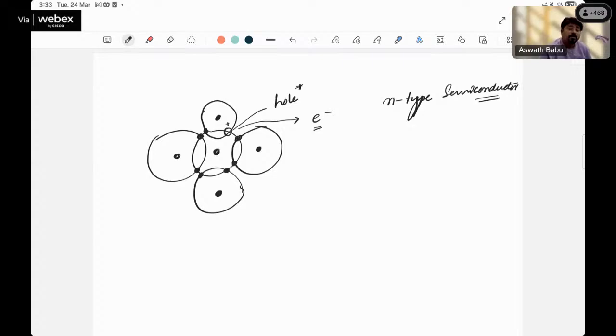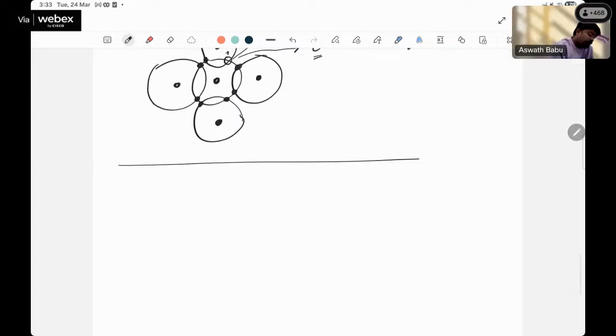So intrinsic semiconductors, we cannot make them a particular type, n-type or p-type. For that, artificially we make something. We are trying to add extra electrons from external means. For that, what people thought is, remove one silicon and add one external atom.